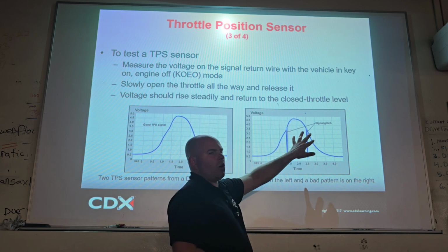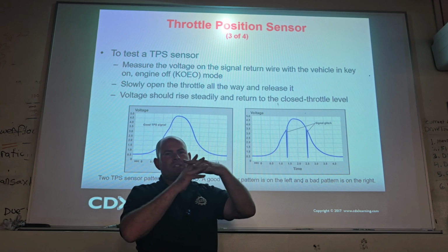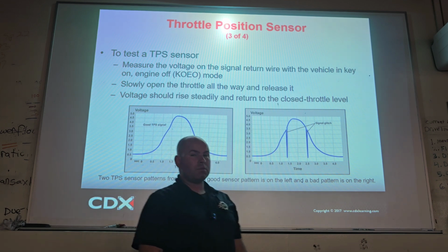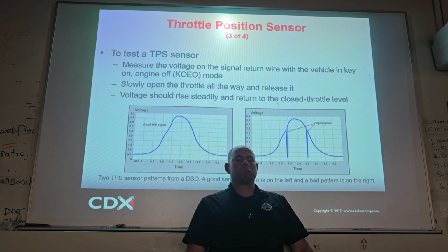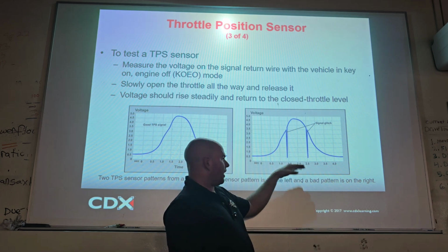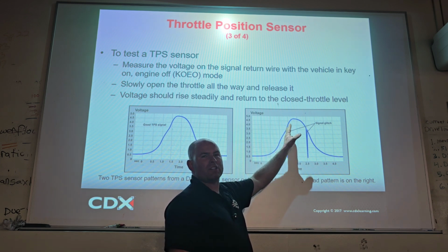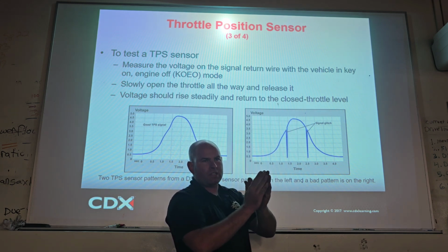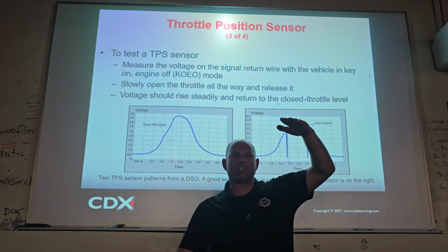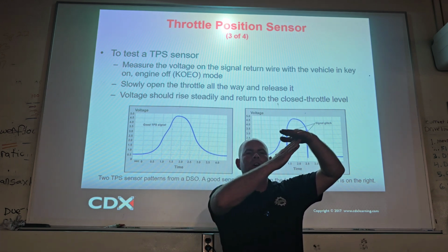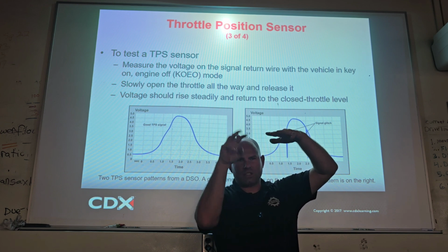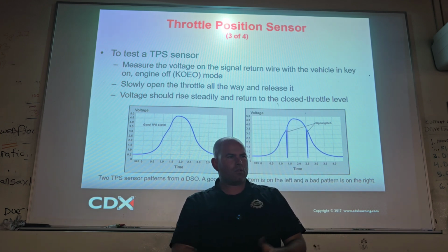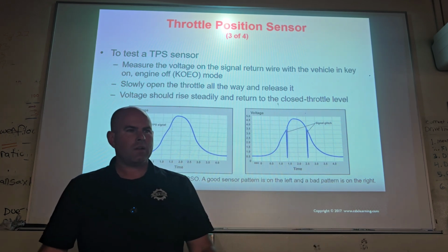That's a notorious open sensor grid on the sensor itself. To be really honest with you, I wouldn't even check this for 5 volts and ground. I'd just be like, oh, yeah, I've seen that before. If it's a 5 volt reference problem, it doesn't consistently drop off in a certain position on the throttle. Make sense? The certain position on the throttle is a thing wiping across the carbon coated surface. Make sense? So there's one area of the sensor that's scratched away or something. Cool? Roberto, go ahead.